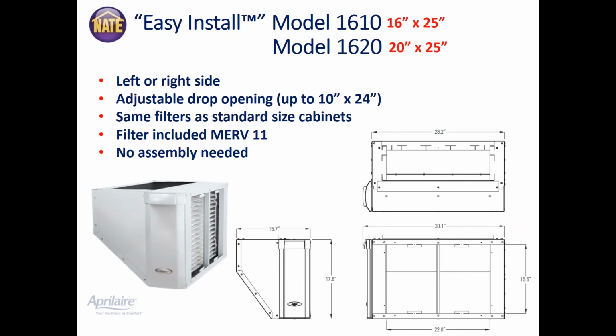Let's talk about our easy install, 1610 and 1620. Those are just different sizes, nominal 16 by 25 inch and nominal 20 by 25 inch. These are designed to make it easier for you, when you're doing equipment changeout, for example, to add in a wider cabinet. So if you had a 1-inch filter slot, there's not a lot of room between the return drop and the HVAC cabinet.